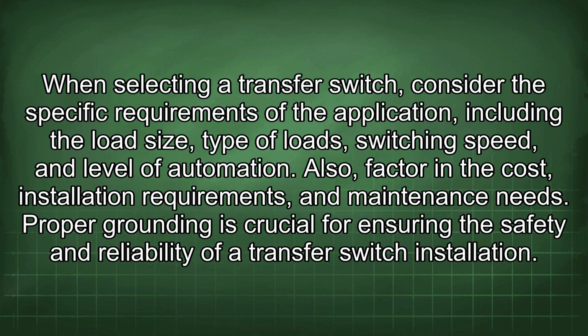When selecting a transfer switch, consider the specific requirements of the application, including the load size, type of loads, switching speed, and level of automation. Also, factor in the cost, installation requirements, and maintenance needs.